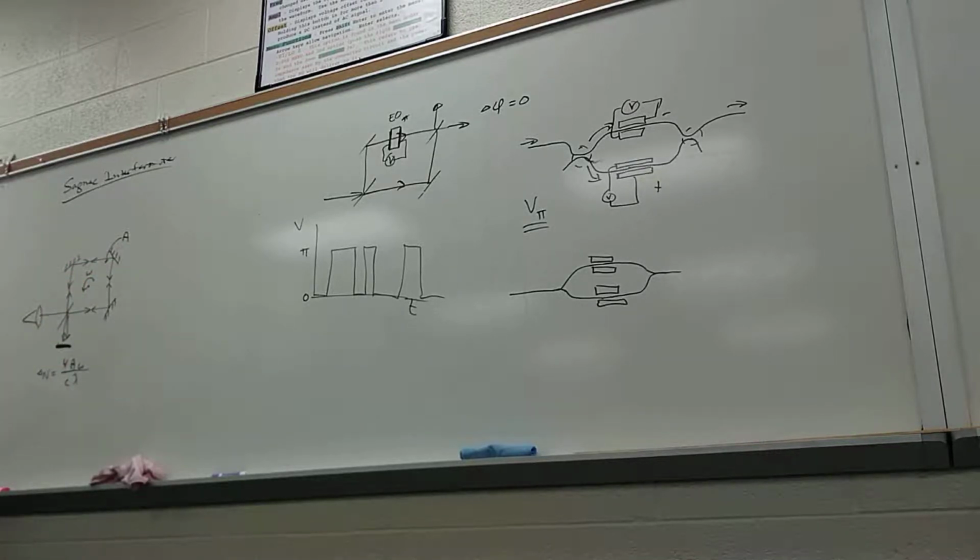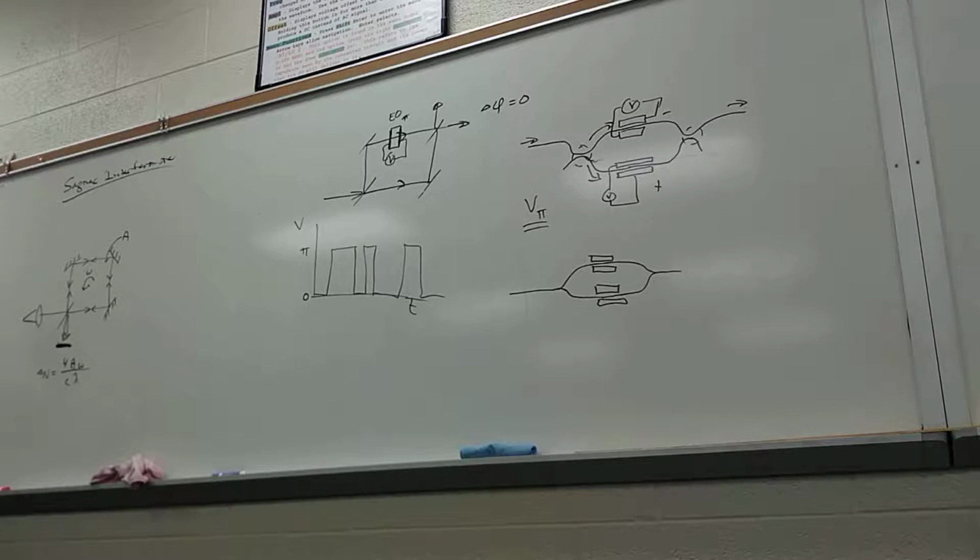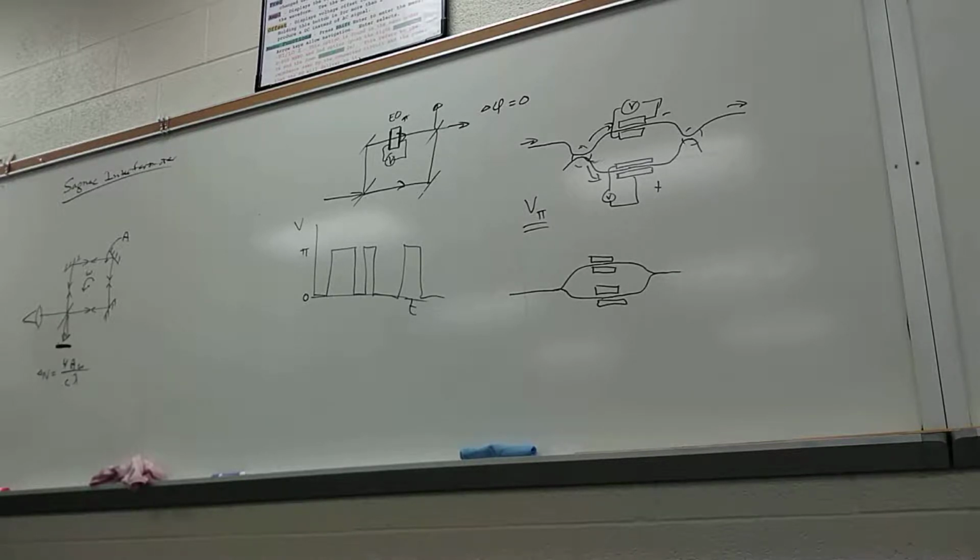So by measuring how many fringe shifts you get, or fractional fringe shifts usually, you can measure the angular velocity of this thing. Now that turns out to be extremely useful, just to tell you how fast you're spinning. Gyros. Yep, this is a gyroscope. So in an airplane, this is how you tell when your yaw changes or your pitch: you're monitoring all 3 axes of rotation with 3 of these things, all mutually orthogonal.